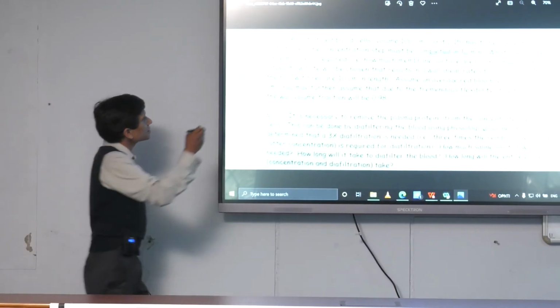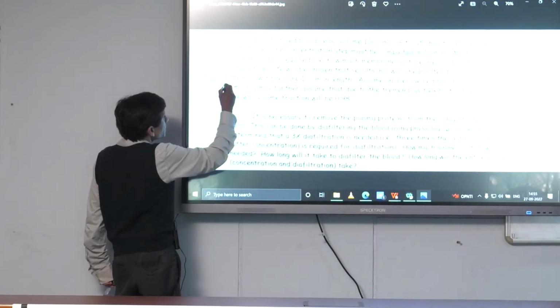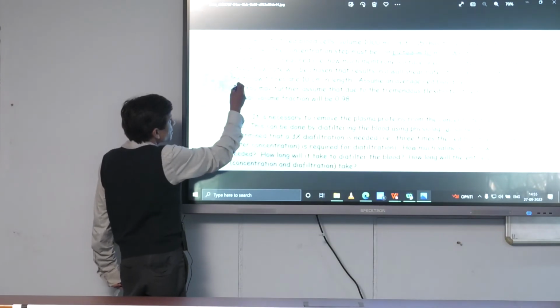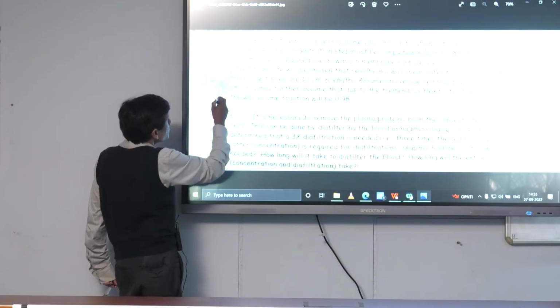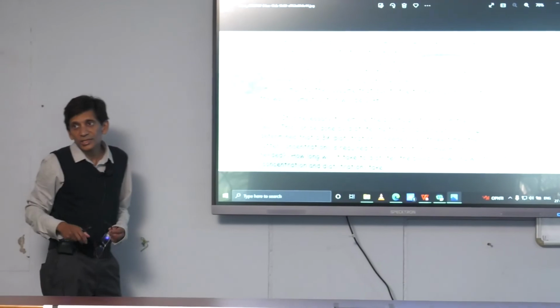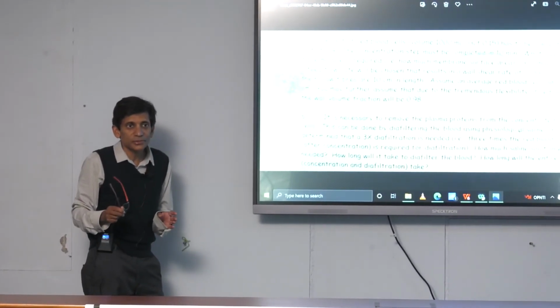But then the flux is equal to what? Q divided by A divided by T, right? The amount you have to process, the membrane surface area, and time. You're told the time is 10 minutes. You really need to try and figure out what A is, and you need to figure out what Q is, but you know what J is, if you can calculate, okay? So that's the problem. Does everyone understand the problem, what you have to do here?